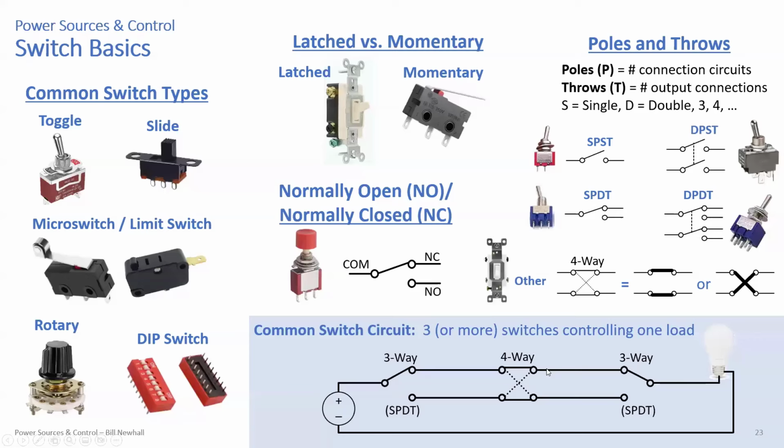And in fact, if you need more switches to control that same load, you can put another 4-way switch in here and keep stacking those up. So that's how you can control a load with multiple switches. Okay, so those are common terms for switches.